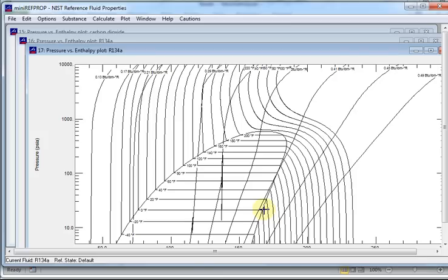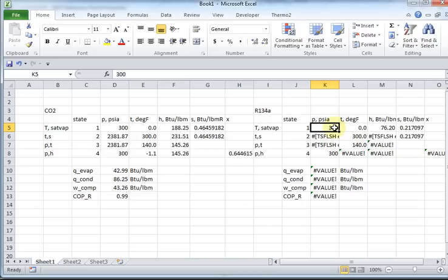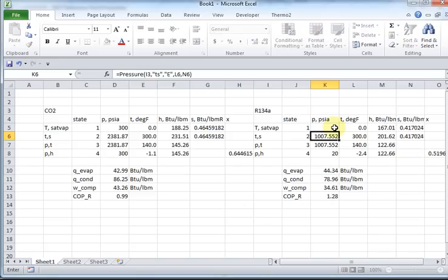So what we want to do is say, okay, it looks like the pressure is going to be about 20 psi. And what about if I'm rejecting at, did I say 140? The high pressure, try to remember these numbers, is around 240 psi. That's a big difference, isn't it? So what is it again? 20 and 240. Let's go back to this Excel spreadsheet. So it's going to be 20 and 240.